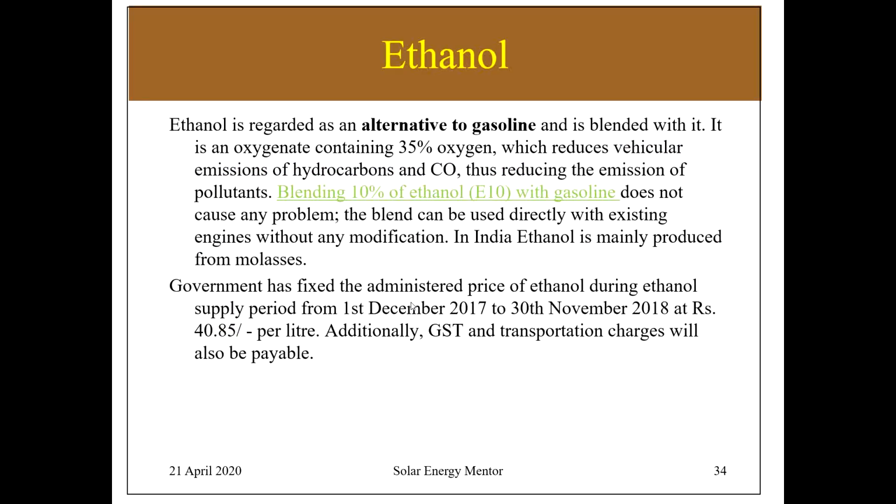Another fuel which is coming is ethanol. Ethanol is regarded as an alternative to petrol, an alternative to gasoline. The blending of 10% ethanol, E10, has been proven. The problem with ethanol is that it contains more oxygen, 35% oxygen, so the temperatures of combustion are higher and NOx formation is a problem with ethanol burning.